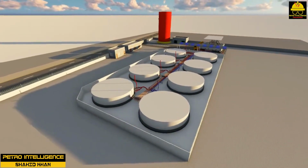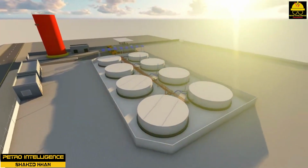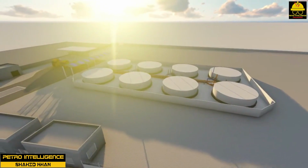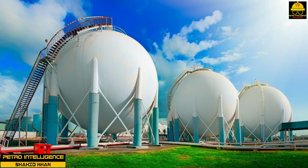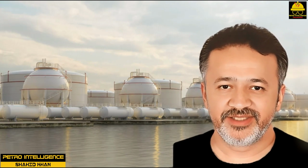Some tank farms include underground salt domes, caverns, and other below-ground storage systems. Process technicians are required to safely operate and maintain each of the complex storage and transfer systems in a tank farm. This picture shows a typical tank farm. Every tank farm will have a list of the chemicals stored on site and a corresponding material safety data sheet, MSDS. Safely handling and storing chemicals requires structured training and financial resources to maintain the integrity of the tanks, pipes, valves, pumps, and instrumentation. New technicians train from 3 to 6 months before being assigned to operate a complex system.